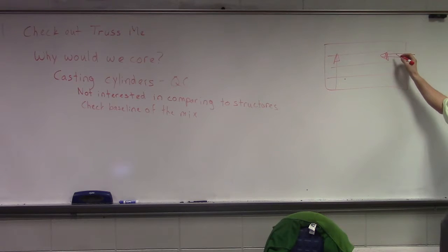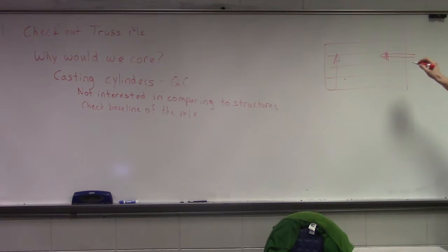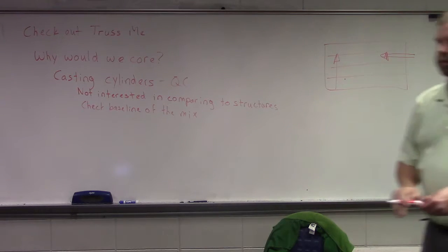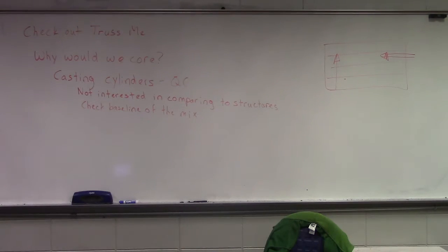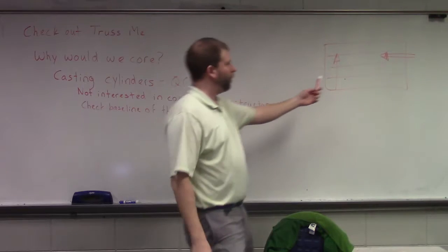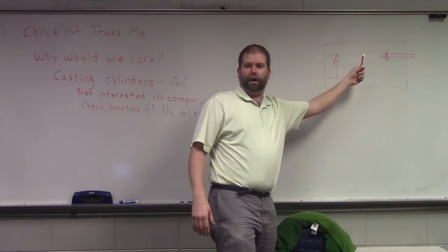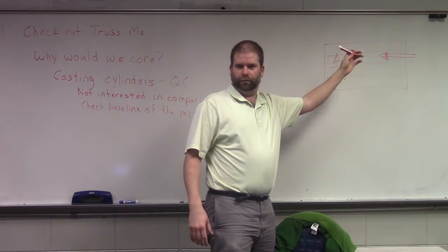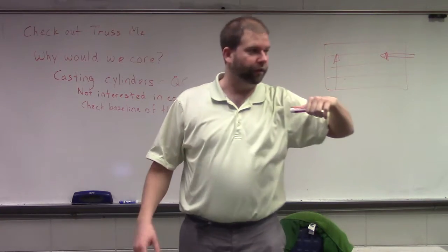The problem with this is when we test cylinders in compression, we also test them the way that they were cast. Okay? So we apply it in such a way so that we're compressing on the top surface. If we then core, but we core horizontally, now we're getting after different aspects of the mix that could take it into account.